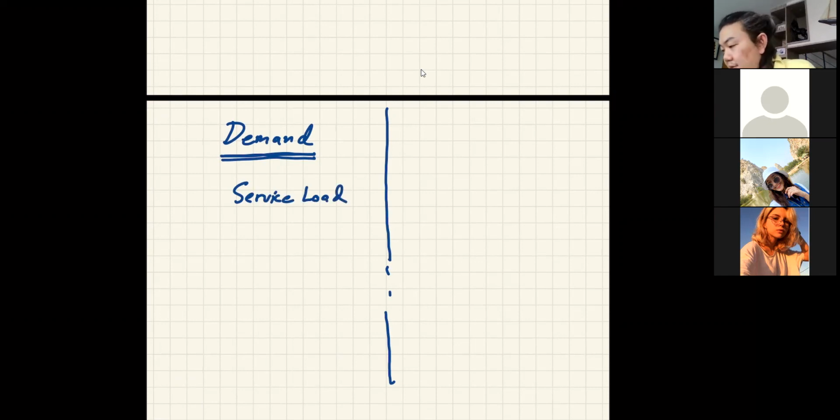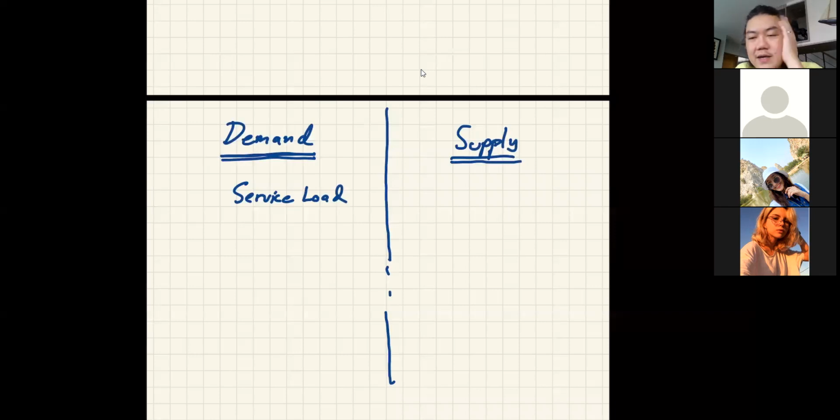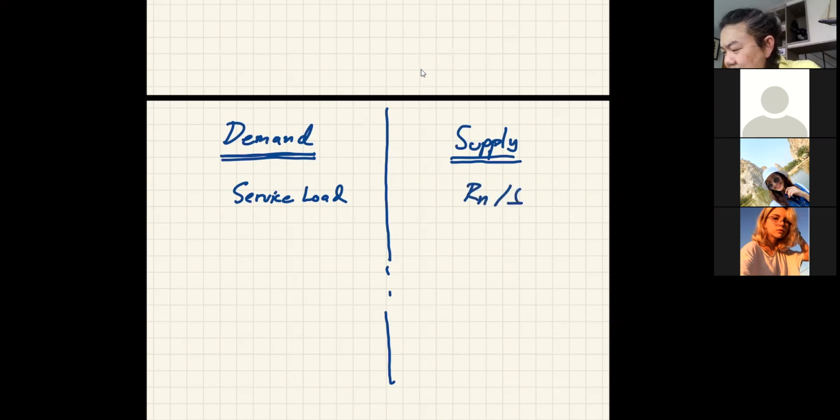Okay, and we are going to design by comparing the forces caused by the service load to the nominal strength of the structure divided by factor of safety. Now remember that this has to be always larger or equal to that.